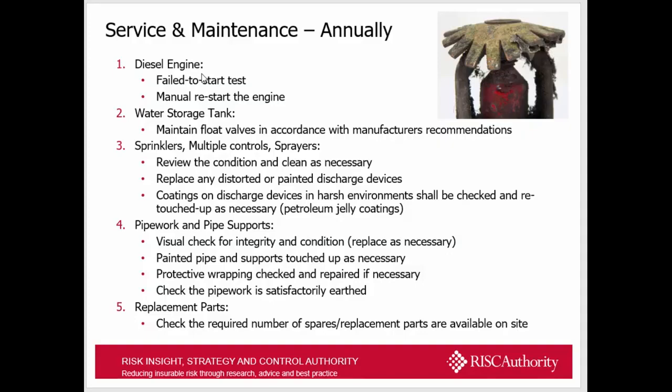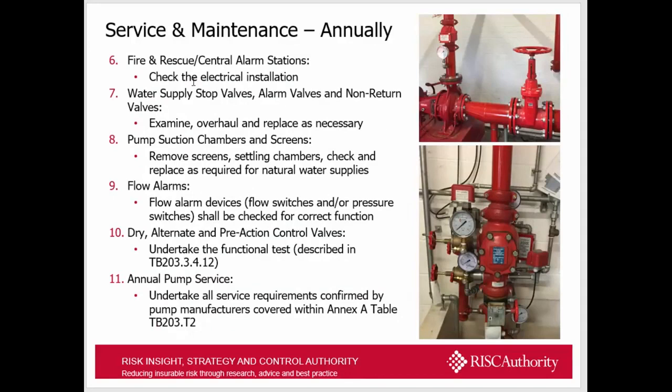Moving on, still on the annual. So again, fire and rescue central alarm stations, check the electrical installation needs to be done. All stop valves, examine, overhaul and replace as necessary. Pump suction chambers and screens, if you have them, clean them. Settling chambers, check and replace as required, for natural water supplies, if you have them. All flow alarm devices shall be checked on an annual basis.